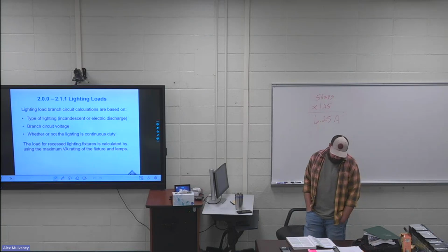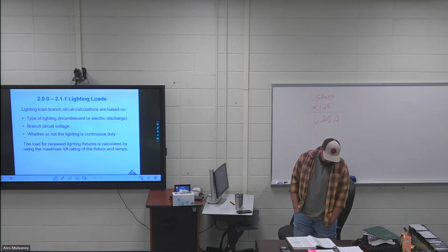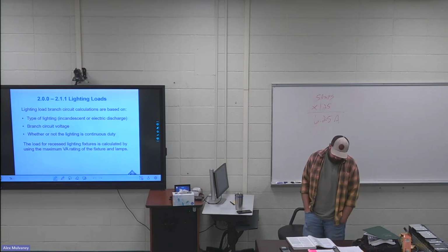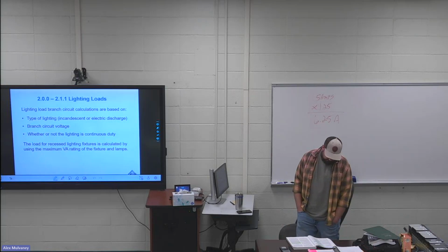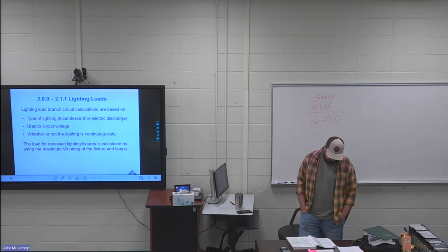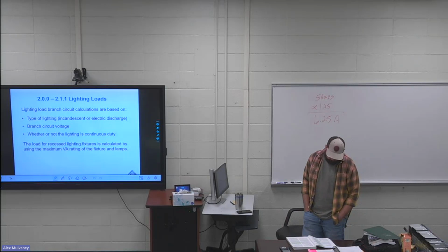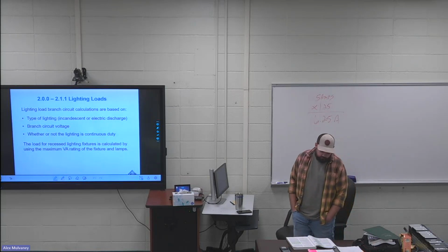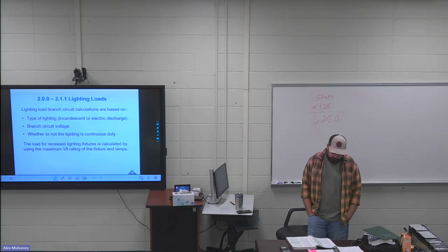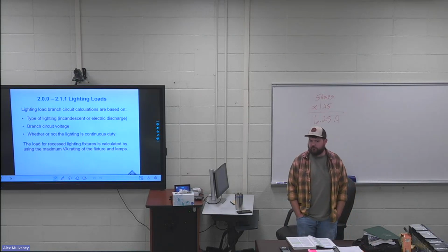Going down to example 1. Incandescent lighting using 150 watt medium base lamp is required for temporary lighting on a construction site. This lighting will remain on all day and all night. So whenever you hear that the lighting will remain all day and all night, what should that trigger in your head? Continuous load. Very, very good.